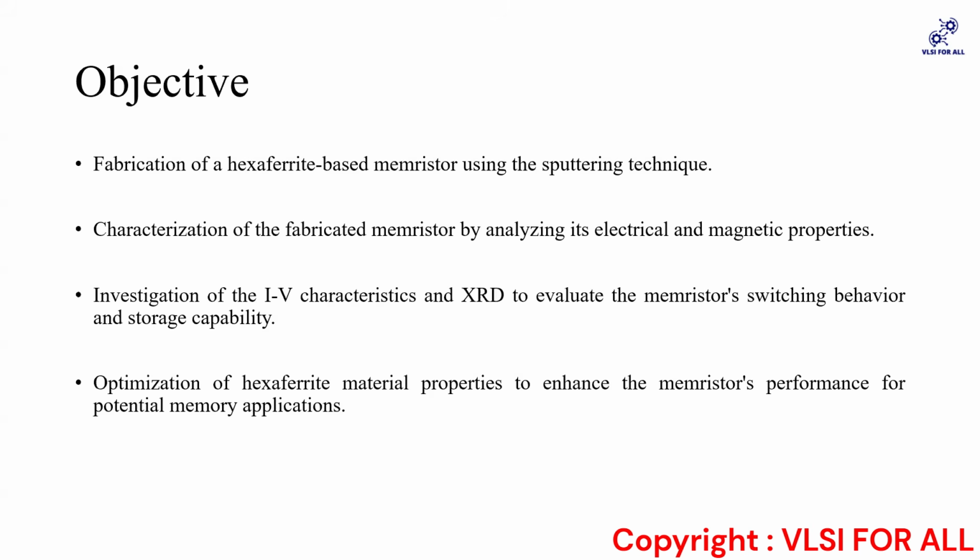Then we are going to analyze the memristor, to check its electrical and magnetic properties. If we have created the memristor, how it is created, what its uses are, and whether the device we created is actually working on its original properties or not. To investigate that, we are going to evaluate XRD and its IV characteristics to check its switching behavior and the memristor's storing capacity.